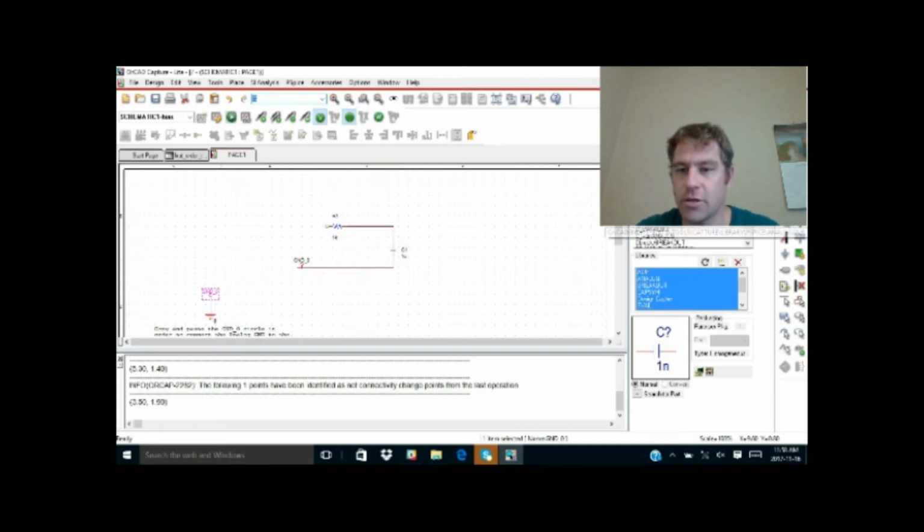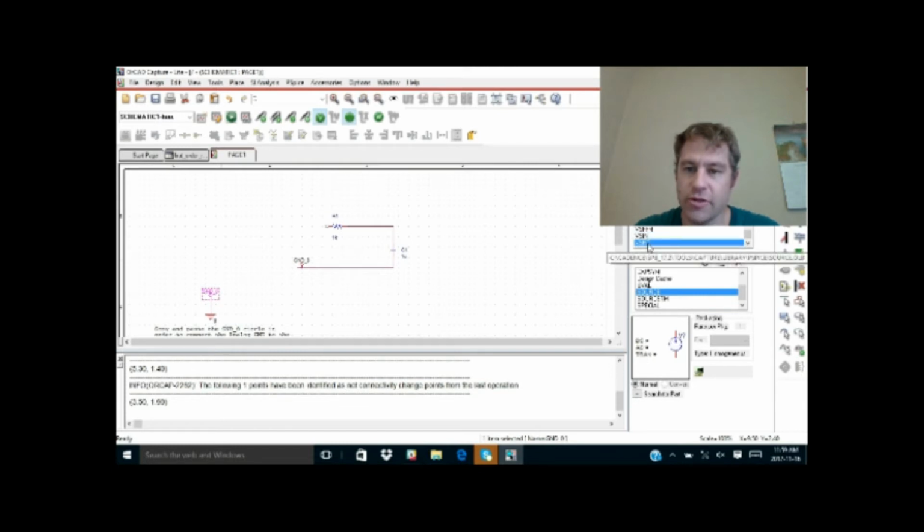So the sources are in the library. Okay, so you have different types of sources. If you go down here, you've got voltage sources, a sinusoidal wave. This one's a little bit more versatile, the SRC one. This one's a sinusoidal wave, as I said before. There's an exponential source. There's a pulse source. I think this one's also interesting, the VPWL. It provides you a little bit of flexibility. VAC is useful to simulate AC simulations, and DC sources are batteries.